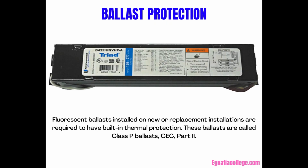Ballast protection. A fluorescent ballast is a regulating component of the fixture which limits the current and provides the proper voltage to start the lamps. All approved fluorescent ballasts installed indoors, except simple reactance-type ballasts, for both new and replacement installations must have built-in thermal protection from the manufacturer. Ballasts provided with built-in thermal protection are listed by the CSA as Class P ballasts. Under normal conditions, the Class P ballast has a case temperature not exceeding 90 degrees Celsius. The thermal protector must open within 2 hours when the case temperature reaches 110 degrees Celsius.